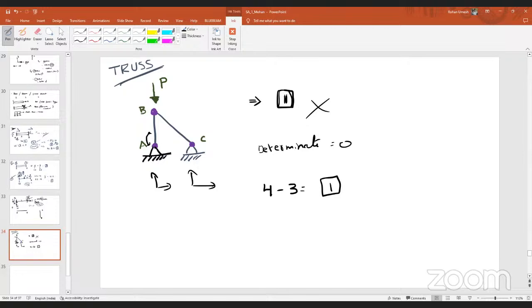In this case, what is the direction of the axial force? The element orientation is vertical, so the axial force direction is vertical. As member AB is oriented along the vertical direction and these are truss cases, it will transfer only axial forces.